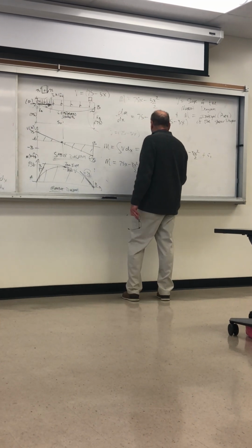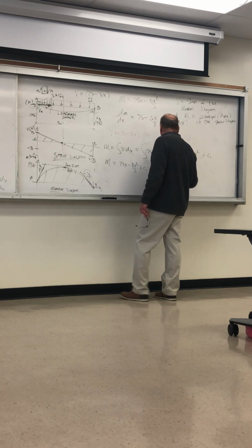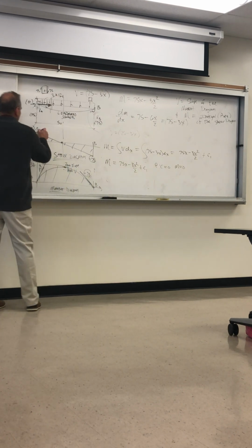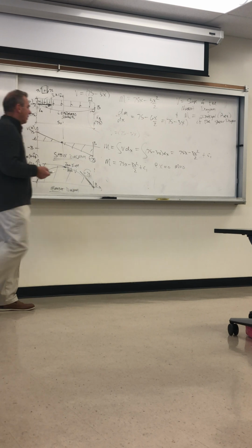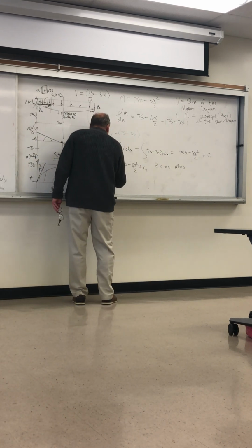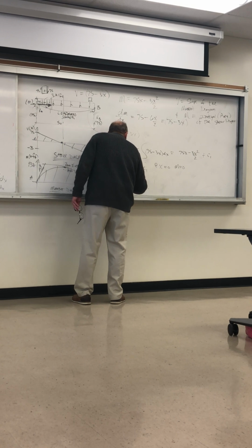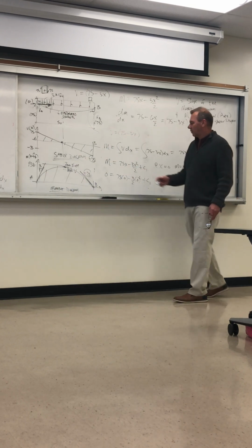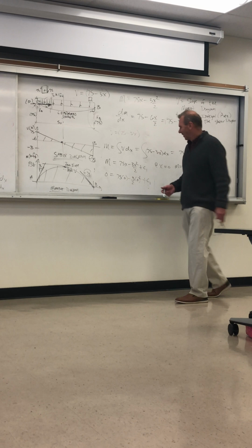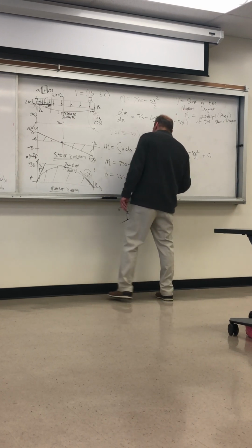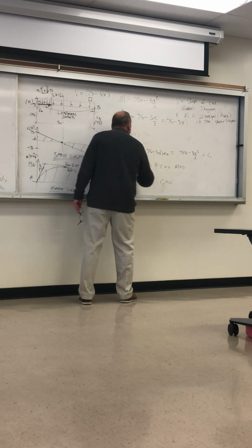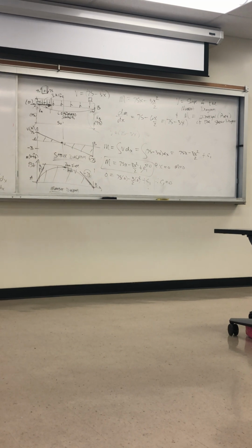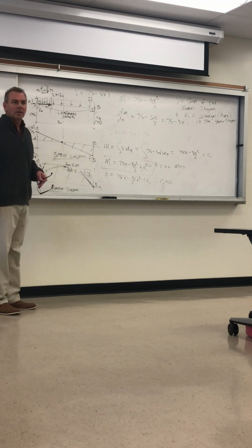And in this case, the constant is going to be 0, because we can say at x is 0, the moment is 0. So if I go all the way back to the left, we know that the moment based on the boundary conditions is 0. So I can put that in, I put 0 here, equals 75 times 0 minus 3 over 2 times 0 squared plus C1, so C1 is equal to 3 zeros added together, which is still 0. Right? So therefore C1 is 0. And this goes out, and then this is your moment expression, which is the same thing we wrote down directly looking at the moments at the top, 75x minus 3x squared over 2.